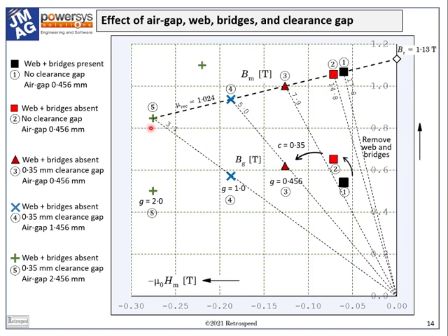So finally, in case 5, we have increased the air gap by another 1 millimeter, and the air gap flux density falls to 0.503 Tesla. So we've actually lost about 7% compared to the original configuration in case 1. The magnet operating point has come down to 0.84 Tesla with a permeance coefficient of only 3.1. So we're definitely entering the range where we are losing in all directions.